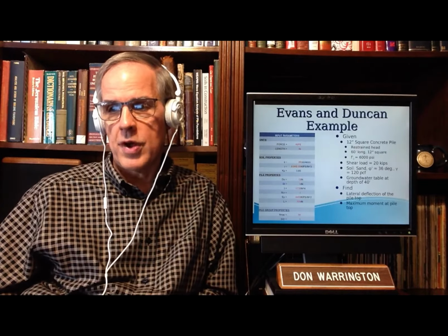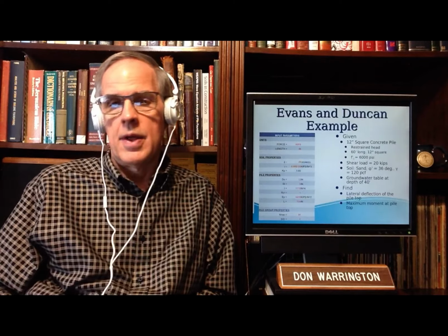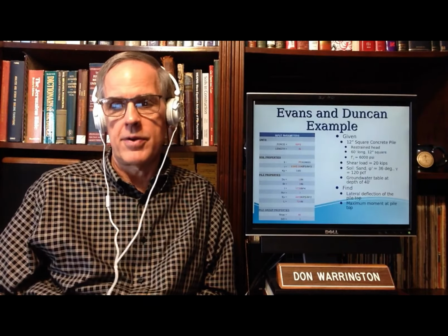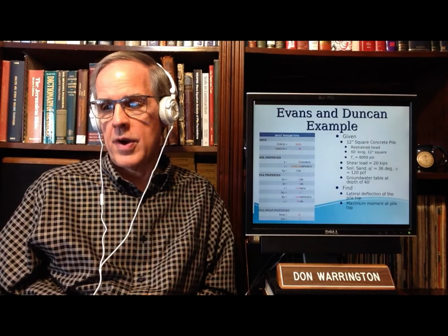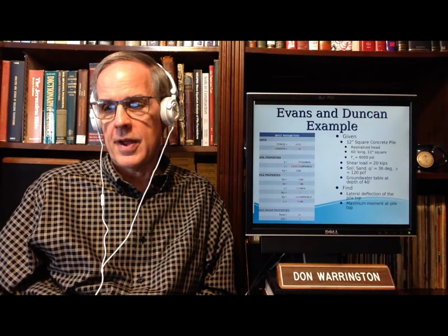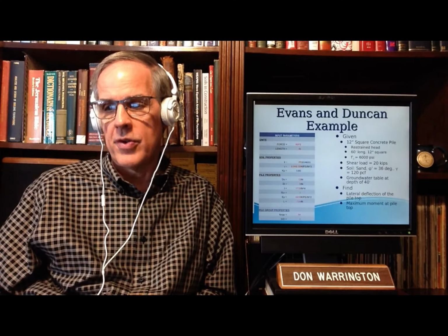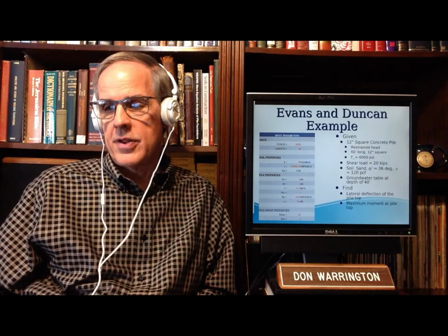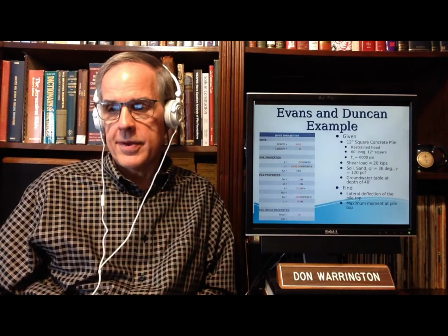So that's a 12-inch square concrete pile, restrained head. And when I say restrained, I mean fixed head. Either fixed or restrained heads are the same terminology. 60 feet long, 12 inches square, and the f'c is 6,000 psi. The shear load is 20 kips, and the soil is a sand, 36 degrees and 120 PCF, with the groundwater table at a depth of 40 feet.